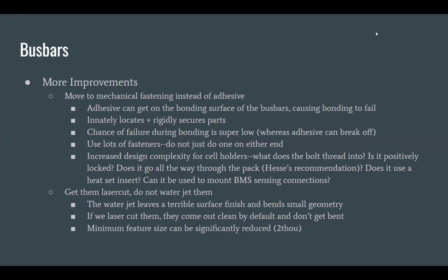Yeah, so that definitely presents the scary situation of, you're right. Number one, that means now you have your battery cells, and then you have a conductive bolt that's going right in between them. And then you now have the bus bar. That voltage is now present on the other side of the pack as well.